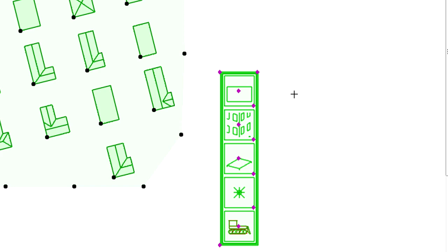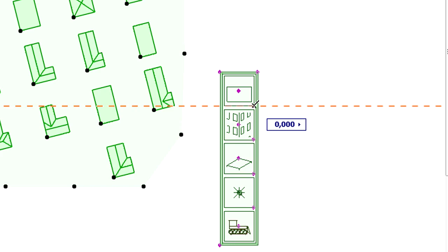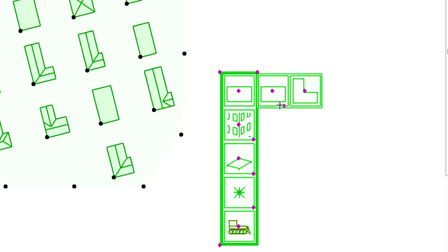The top icon of the palette allows us to access and modify building forms. Let's click and then drag the hotspot at the lower right corner of this icon towards the right to display additional building forms. Now we can see all the available building forms for a selected random city object.